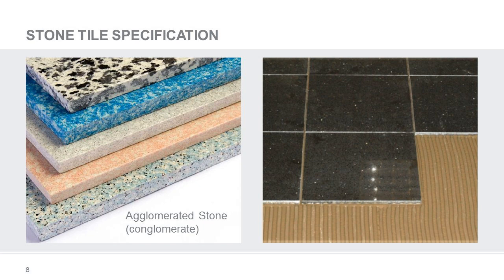Some products contain resins and mineral fillers that may expand on wetting. This can lead to warping, resulting in lippage at the tile joints. It is also worth mentioning here that it's recommended to use low alkalinity rapid drying systems with the agglomerate stone.